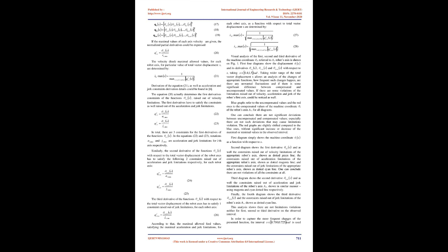Besides the given desired poses, additionally machine configuration trajectory planning is very important in composite manufacture, since a large number of machine coordinate vectors need to be interpolated through the G-code points, and the tool path has to be controlled and highly accurate along all the path. In the online interpolation procedure, but in offline as well, the iterative numerical compensation algorithm calculations need to be performed very fast, and in the online case in real time. A challenge is the additional check if such changes in the machine coordinates due to compensation cause unwanted changes in feed, acceleration, or jerk for each of the robot or machine configuration drivers, and eventually violation of their limitations.